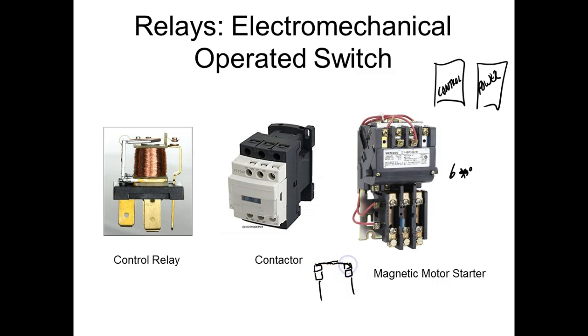What it does is there's a spring in there, and this thing kind of floats. So what happens if the thing breaks and one of the contacts is trying to freeze, then it would automatically tilt up and break the other contact loose. So a lot of the relays that you see in industry use what we call double break contact. And a lot of the push buttons do too. So you can kind of see how those contacts float in there.